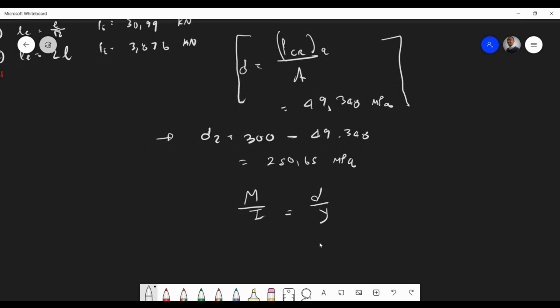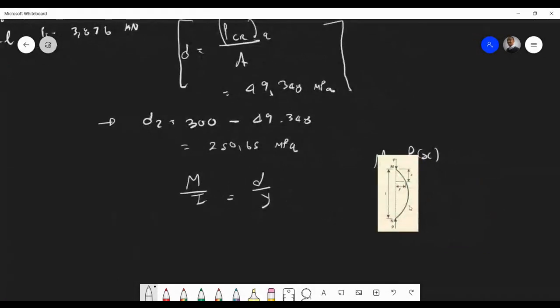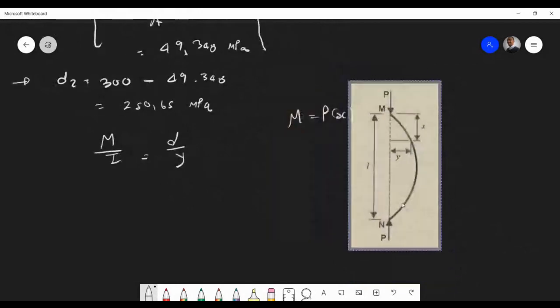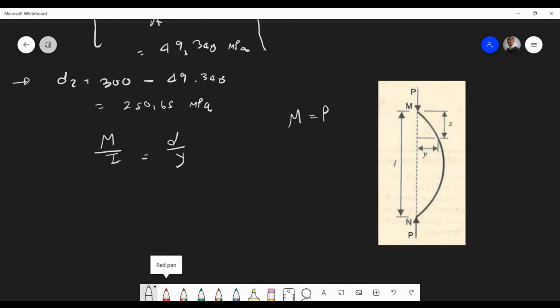And what we need to do is find the moment. The moment is going to be P times, I'm going to call it X, and what I mean by X is this distance. Because remember, they use the same concept from deflection of beams, which I think Alex was talking to. Obviously it's called Y, you'll see it now, but remember, at the end of the day, this load is producing a moment P times Y, right? In this case I should actually just call it Y here, but you get the idea. So what they're asking for is this distance, right?